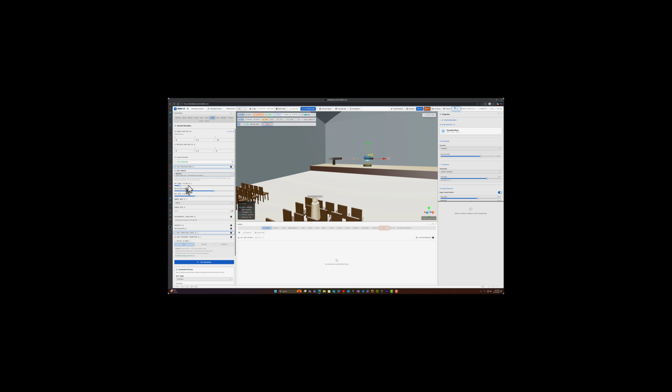Under the hood, NEBULAB uses a hybrid approach that combines ray tracing with a wave-based solver using FDTD, or finite difference time domain, which helps capture low-frequency behavior more realistically. For this simulation, let's increase the ray count from 25,000 to 50,000. In high-precision workflows, you can push much higher ray counts, but for a quick demonstration, 50,000 is a great balance.